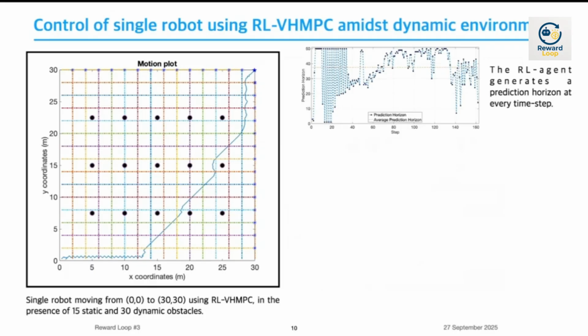This has been experimentally verified, as well as in the literature. I found that very few robotic applications use a prediction horizon greater than 50; they maximally use between 0 and 50, or we say 1 and 50. The prediction horizon value is a natural number, it cannot be 0.